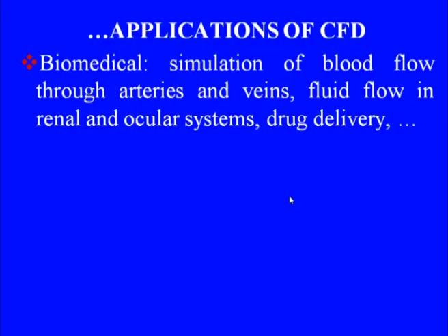One of the most exciting applications in the past decade or so is the application of CFD to biomedical problems. The prominent applications have been in simulation of blood flow through arteries and veins, fluid flow in the renal and ocular systems, and drug delivery aspects. In fact, the recent trend is to perform what doctors call a patient specific simulation.